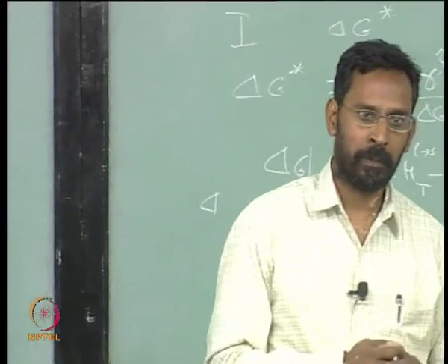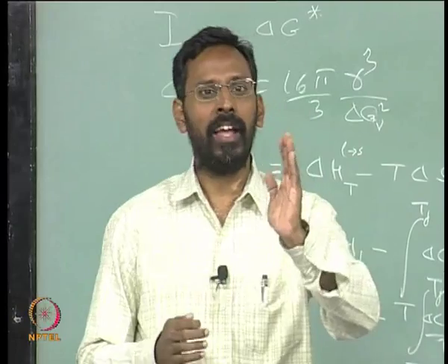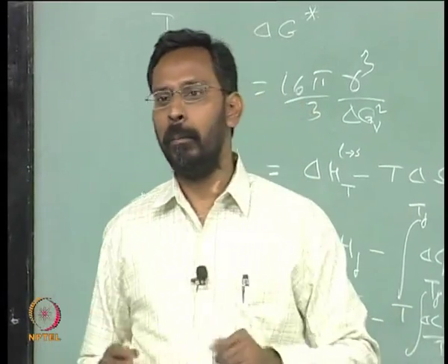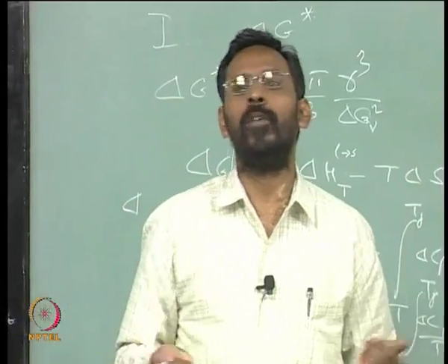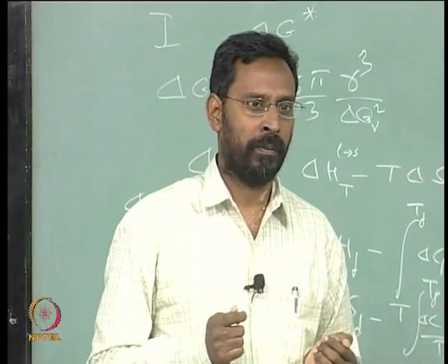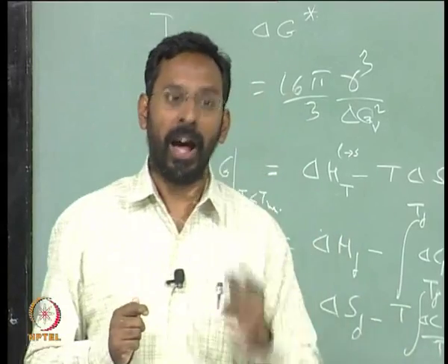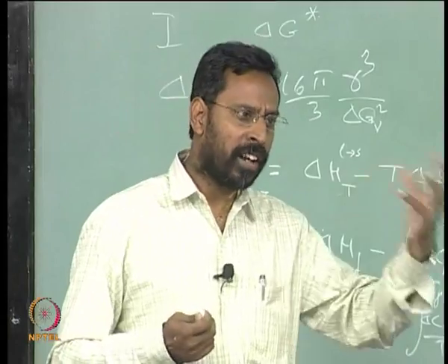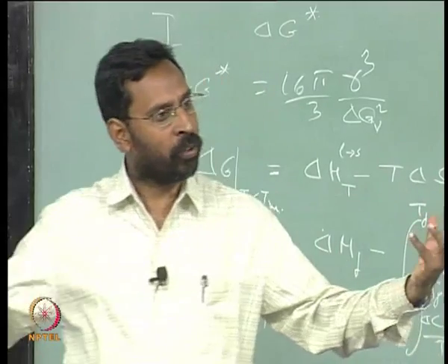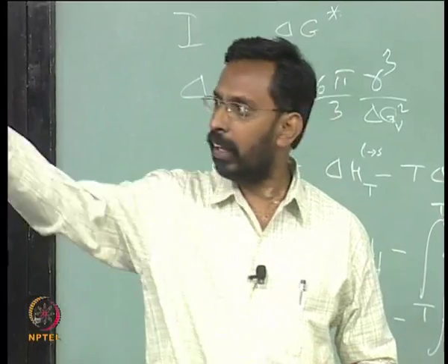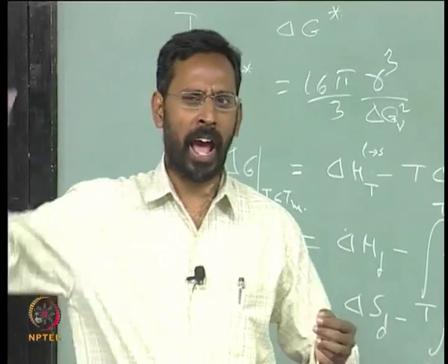For a liquid, they say above 660 for aluminum it is valid, below 660 that particular A, B, C are not valid, because nobody has measured them, nobody can measure them unless there is a liquid which can be easily undercooled and still kept as liquid before it actually crystallizes, something like a glass forming liquid, like a silicate glass you can happily undercool.